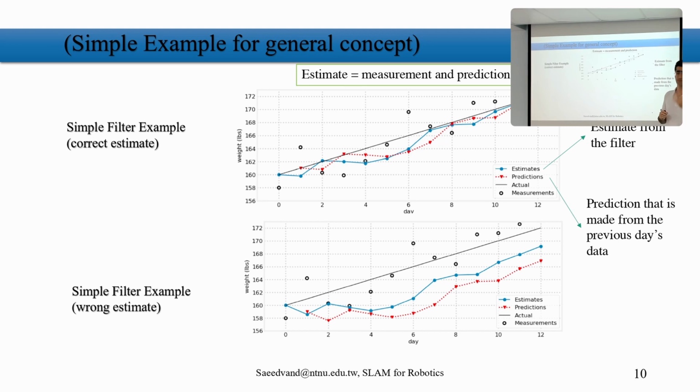So based on this knowledge, and after learning the Kalman filter and extended Kalman filter, you can use it in different applications, not only robotics. You just need to plug in what you need as prediction over here and try to estimate it. This prediction is not limited only to control commands. This can come from any source, any sensor reading, or the prediction that we have based on the data that we have.